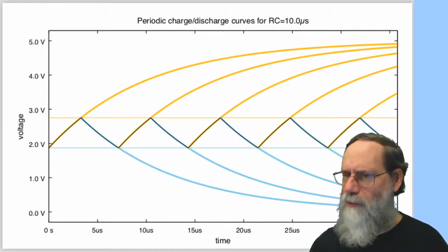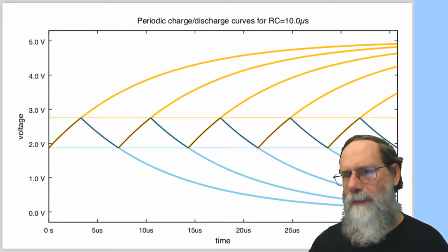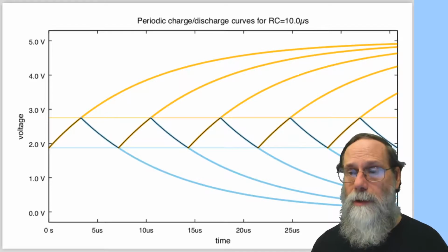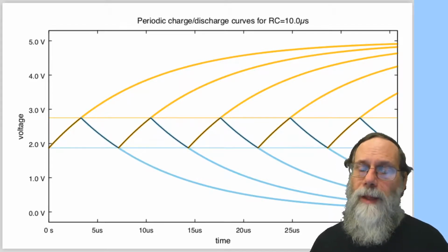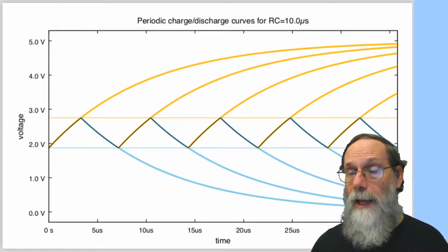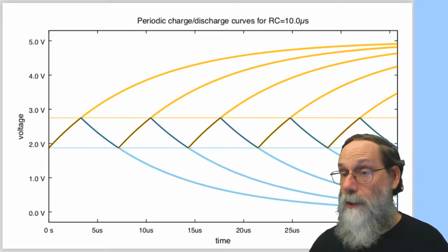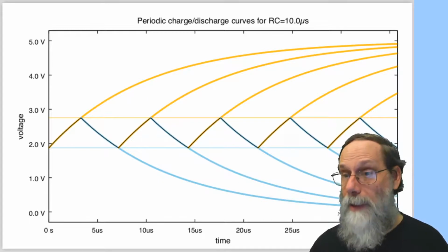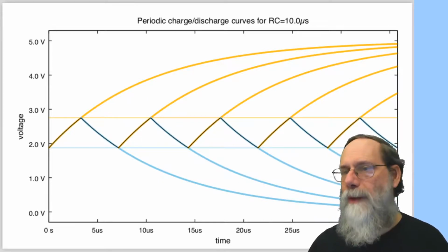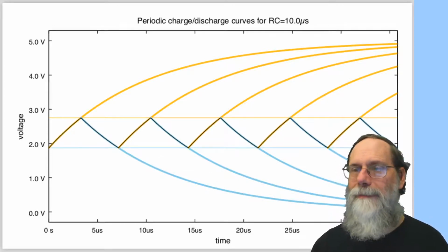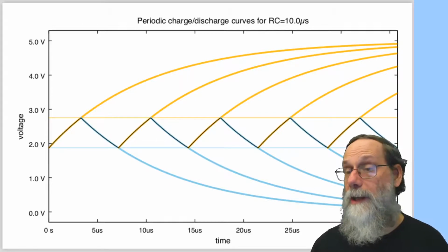This thing doesn't really have a straight line for the two parts of the triangle wave, but you can approximate it as that, and that gives you, you can look in the book, a very simple formula that's actually simpler than this stuff with the logarithms. It turns out that neither model is completely accurate because we've ignored some phenomenon with a Schmitt trigger. And as a result, it doesn't really matter too much which of these two models you pick. They're both somewhat inaccurate, and they're both good enough. So pick which one you like and apply it to get both the charging and the discharging time to get an estimate of the period.